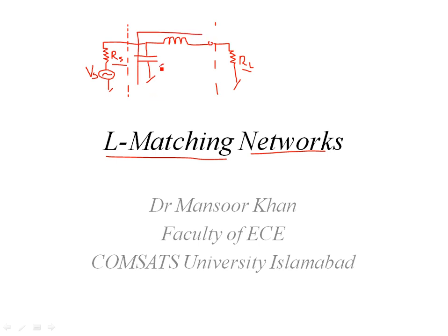So you use these LC elements, which are passive lossless elements, between the voltage source and the load in order to maximize the power transfer. It could be the other way around as well. You can have a capacitor over here, for example, or an inductor over here instead. So it's again an L. Or you can have a capacitor over here and an inductor over here. That's why, in the literature, they are commonly referred to as L matching networks.